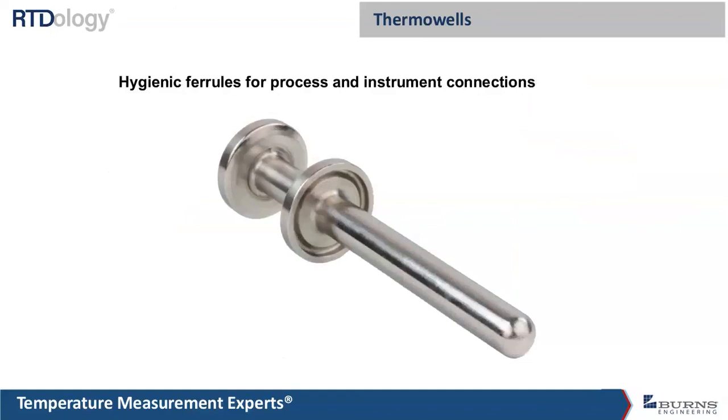One of the other things for sanitary Thermowells would be to know a good estimation of what the surface finish is. And typically just by looking at them, this one probably has about a 20 micro-inch average surface finish. It looks a little dull. There are no visible scratches. If you rub your fingernail on it, you're really not going to have it catch on any scratches.